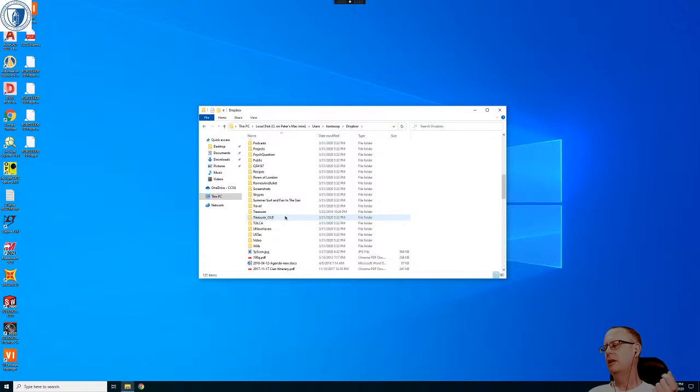If you change the statements for S and C in order to make the sum equal to A exclusive or B, and you change the carry output to be A and B, then that will give you the full marks for lab 3. No, so again, Ray, I want you to implement exactly the half adder using VHDL.